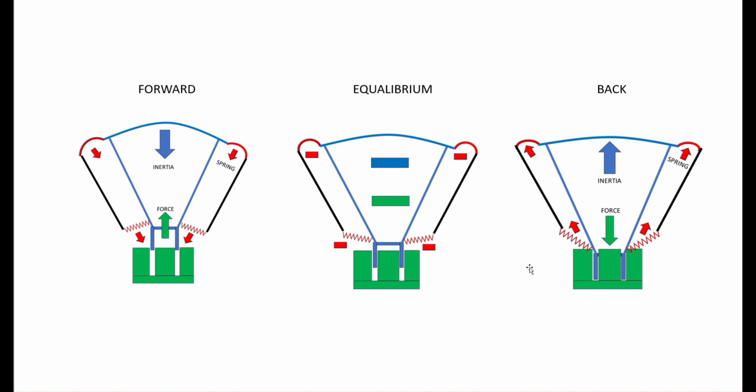Now compare that to a soft spring, right? This is a soft spring now, and so these forces are much weaker, which means that it's easier to push the cone. The cone can extend further because the spring is a weaker spring, so you can push it further. When the spring pulls it back to its resting position, that's going to happen slower because the spring forces are less.